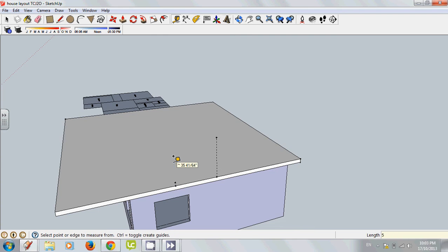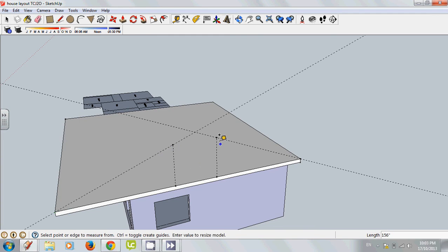So typically when we talk about roof slopes, we are talking about rise over run. And I'm having a problem here, hold on. 5 feet, enter, there we go. And so that represents the angle of the roof. So I put those markers up there, then I connected a construction line from the corner up to that mark, and then it creates a line that passes right through and intersects in the middle. And I'm going to do a couple other lines that are going to represent the fascia on the gable end wall, and you'll see it kind of come together after I'm done.